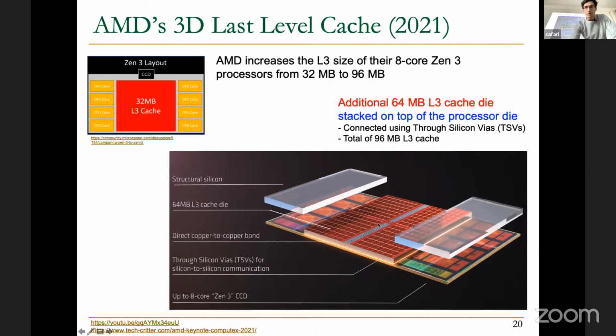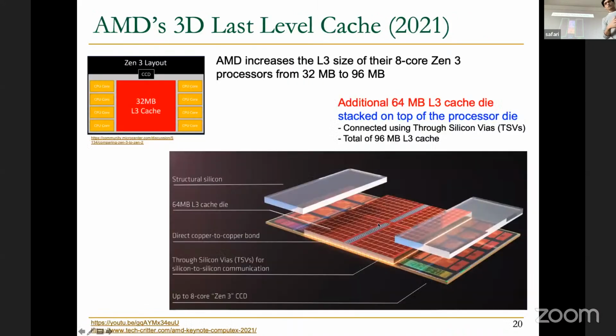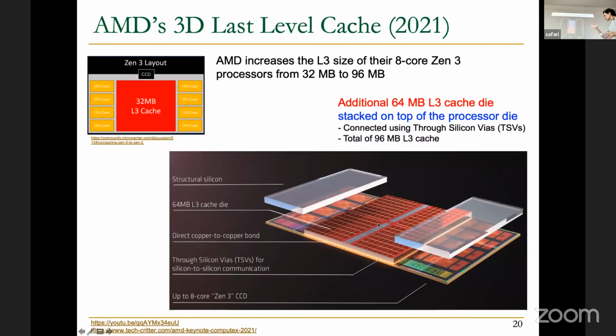And not only AMD processors, of course, similar things you can observe in IBM processors. For example, this is an IBM Power 10 from 2020. Also, most of the chip area is occupied by L3 and L2 memories. Or even more recent is this M1 Ultra from Apple from 2022, where inside the processor chip itself, there is a lot of SRAM, L3, L2, as we have just seen in the previous pictures, but also a lot of the entire system is occupied by DRAM or by storage.